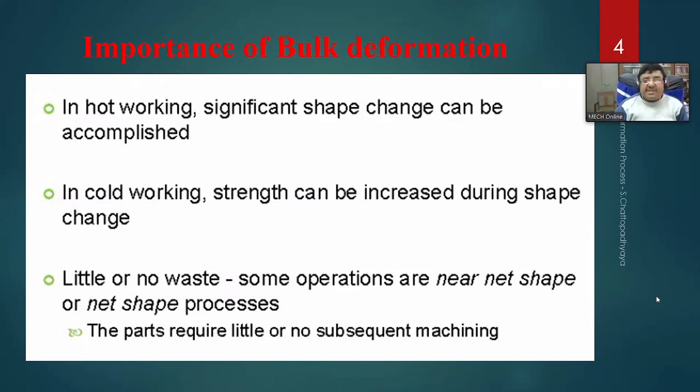So these stresses will not be there if recrystallization occurs, but stresses will be induced if you do cold working, in the form of strain hardening at the surfaces. Very fundamental things I'm telling you, which you should not afford to forget in your lifetime.